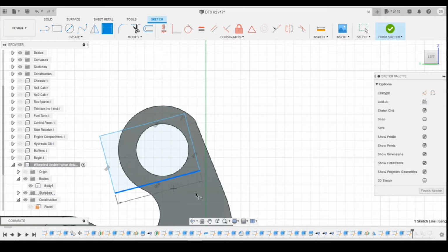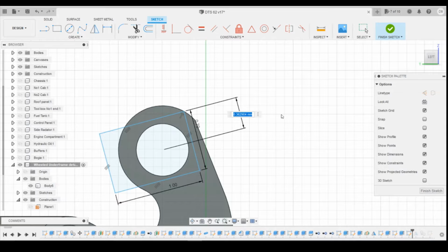Okay, let's define the length. So that's going to be 1 millimeter. Define the height. It's gone the wrong way, so let's delete that. Try again. So move 0.7. We'll go from the midpoint of that circle, then 0.35. That puts the midpoint top bottom the same. And distance from there, if we go 0.35 again, it's sort of square except the extra bit on the bottom here.